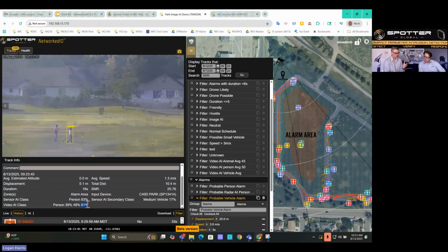So I want to balance that. I want to say, okay, if I have a real person in that location, I want to alarm, but not put it too low, so I alarm on things that aren't necessarily people, because like all technologies, it's not 100% accurate. And so it's a matter of weighing the different options and balancing out that threshold where you keep a probability of alarming of higher than 90% while keeping your false alarms as low as possible. Okay. And that's how you would optimize.